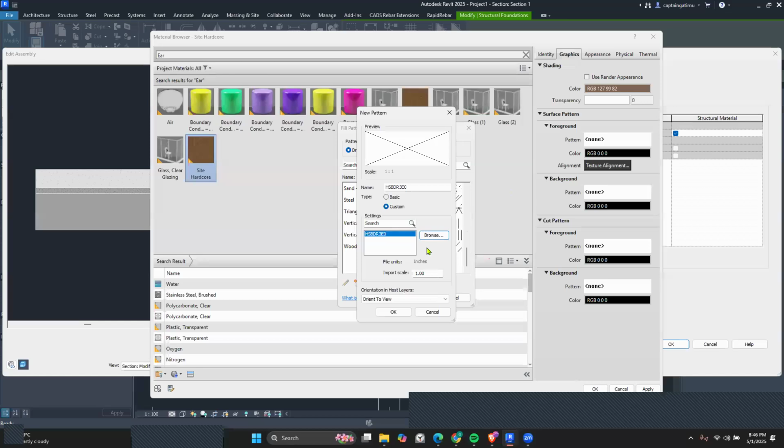After you have imported it into your software, you could change the scale to something really, really small. You can see at the moment it's not visible. It's just a plus sign. To make it more visible, you need to reduce the import scale. So we could reduce this to 0.09. Okay, let's see how that looks. You can see now the pattern is becoming more pronounced.